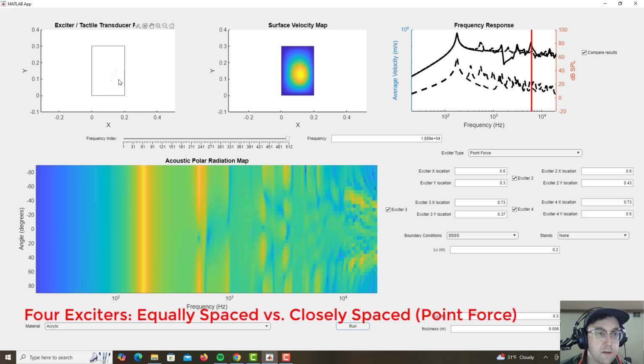Yeah, that looks pretty good. That's probably about right. Sort of isolated around there. Yeah, you can tell where the exciters are in some of these patterns. Like this one, I can see the 4. And again, probably worse low frequency response with more peaks, but we've smoothed out a lot of the really sharp stuff in the mid and high frequencies. Mids especially. Those mids were pretty terrible with the 4 equally spaced exciters.